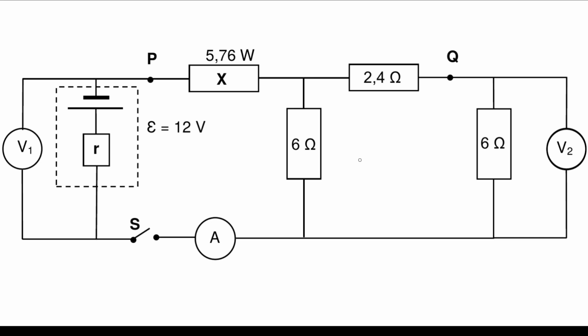Here we go. A slightly more confusing circuit, but let's do this. You find your battery. You choose a side, doesn't matter which one. Let's go up this time, just to be contrary. And we move up. We hit a fork in the road. Down there is our voltmeter. No current through a voltmeter. Yay. And we start traveling along. We hit a resistor, no problem. The current goes straight through a resistor. And we hit a split.